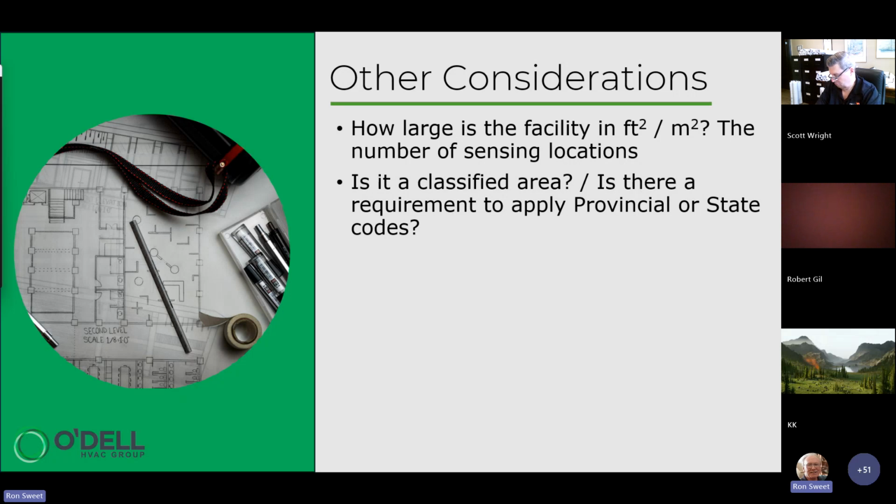And typically gas detection and ventilation components are in explosion-proof housings. In the case of fans, you're going to have spark-proof motors, which again are designed such that they will not generate a spark and therefore be a source of ignition.